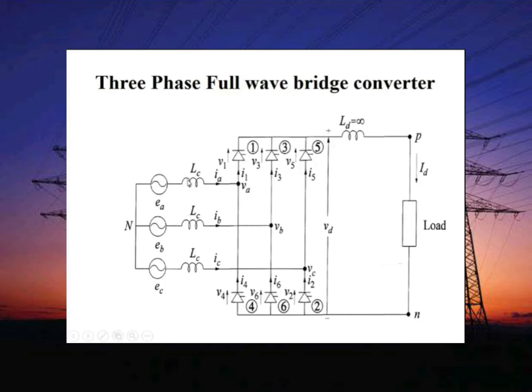The valve bridge is an array of high voltage switches or valves that sequentially connect the three-phase alternating voltage to the DC terminal. So the desired conversion and the control of power are achieved with the help of this valve. The basic model of an HVDC converter is a three-phase full-wave bridge circuit, also known as a graetz bridge.